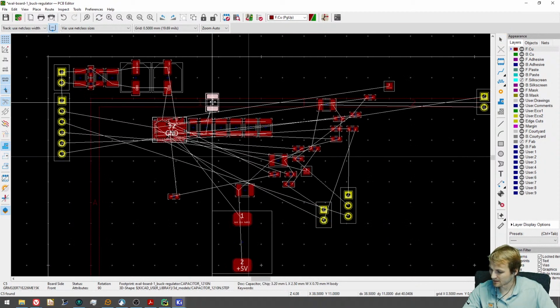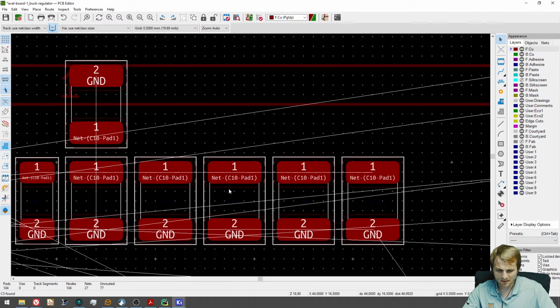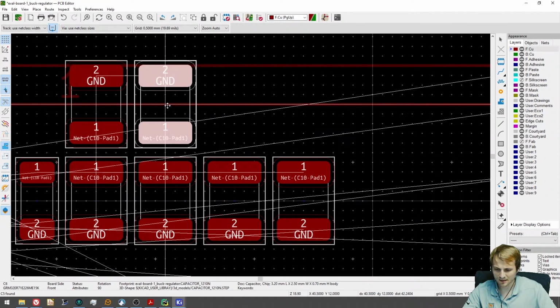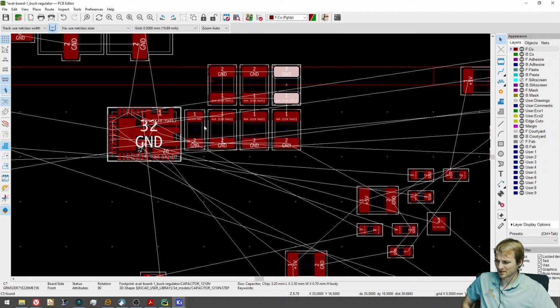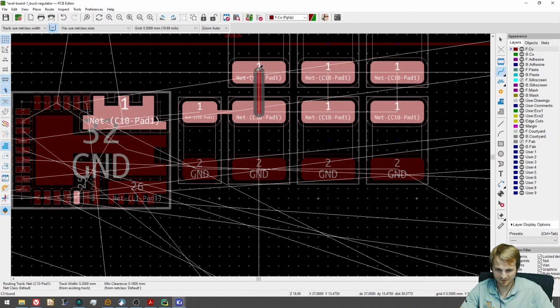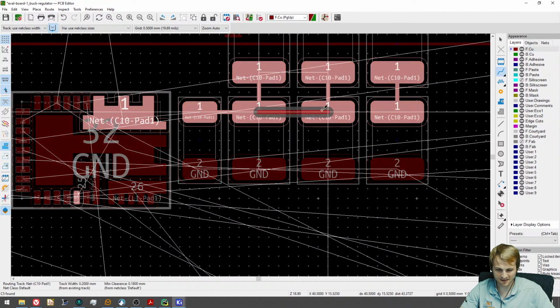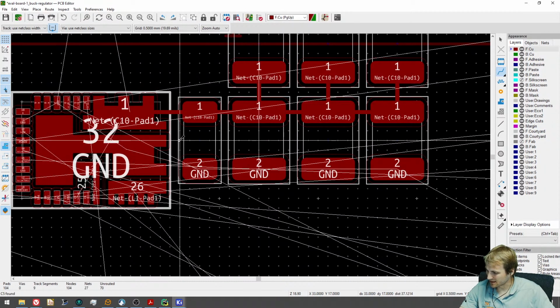Man, these are a lot of caps. Is it GaN? I don't believe so. If it was, I assume they would have bragged a lot more about it than that. And normally this layout's going to seem quite excessive with just how many caps and everything there are. Keep in mind it's going to have to be rated for 15 amps in a buck, which is really, really high. So it looks excessive because it kind of is. But we'll see. What's the height of the IC? Will it take a heat sink with the caps close?